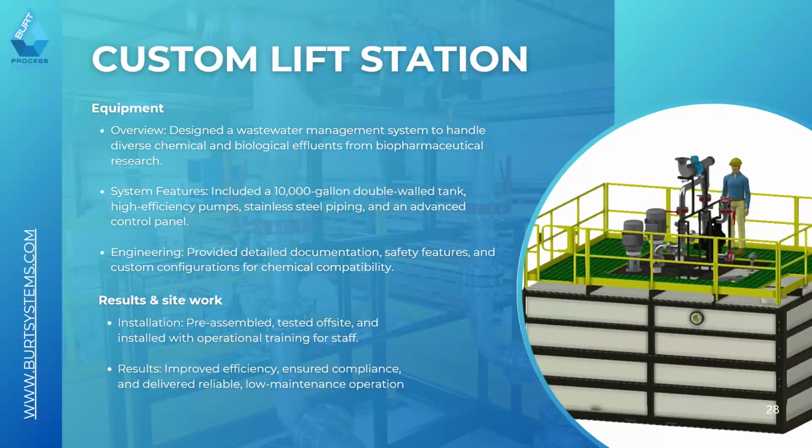If you have very high fluoride water, then we need to look at using a probe that is actually designed to monitor that, because the fluoride water itself can actually drain out the probe and cause it to go out of calibration quicker. So I don't specifically endorse any brands in a webinar like this, but I do think there are probably 7 or 8 that are out there that range from more economical solutions to more process-driven solutions that really depend on what you want to do.